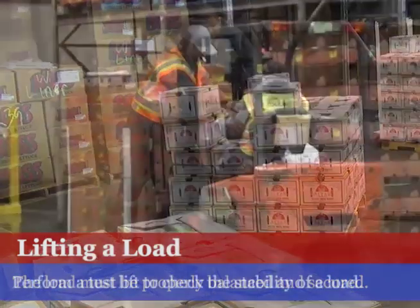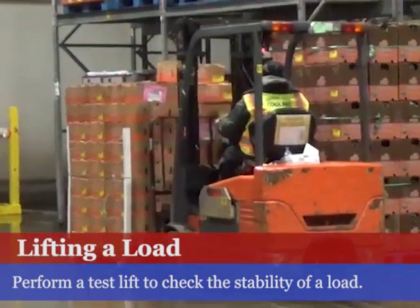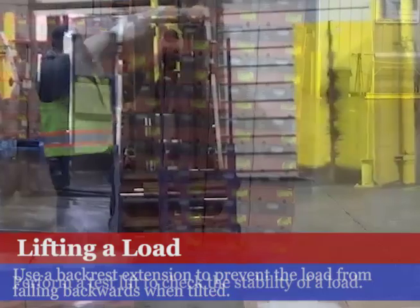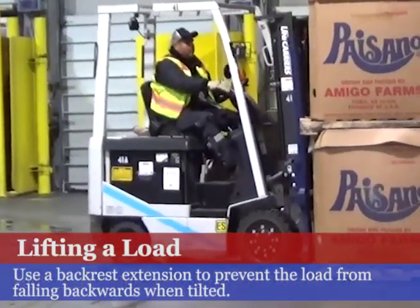If you are not sure of the load's stability, perform a test lift first. If the load seems unstable, put it down and rearrange it. If there is a possibility of the load shifting backwards, make sure that a backrest extension is installed.